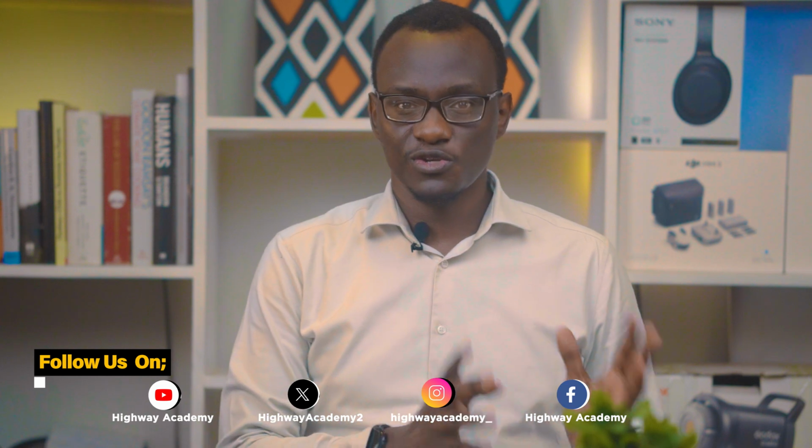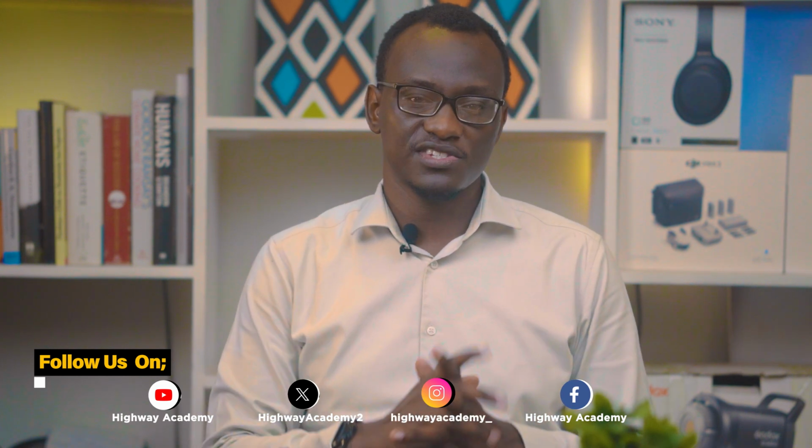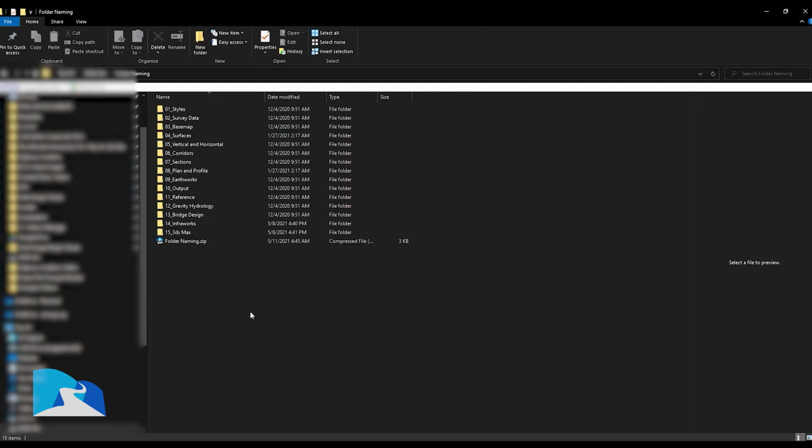Now, there's a video that's going to play that's going to talk about the folder organization we use when you're designing highways, which is a zip file. Just download the zip file and it shows you the folder naming that you're going to use. And this folder naming makes it easier for you to know where to put your alignments, where to put your corridors, where to put earthworks, or where to put the pipe culverts. Trust me, when you don't have an organized file folder, you come back years later and you cannot remember where files were. This lesson is about the folder naming structure.